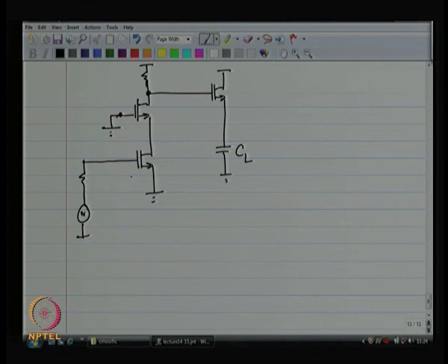How the cascode works is, you basically create a change in current. You are applying VGS across this device, you create a change in current. This change in current has nowhere to go but through the drain of the second device, and basically the gain that you see is this change in current times the output impedance looking into the drain of the second device. Now, the output impedance looking into the drain of the second device is going to be what you see looking above, which is that resistor or whatever you have over there, and what you see looking below. What you see looking below is a much larger resistance, right.